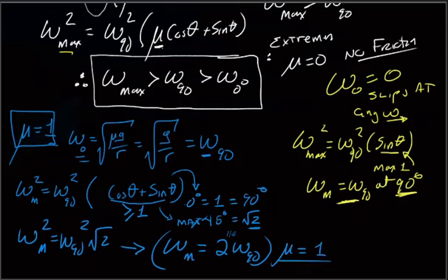So under all cases, we're not able to reach this at a constant omega if we start at 0 or we start at 90. We would have to have some alpha to reach that value. And for fun, you could try to find that alpha as omega final minus omega initial over t. And if we want to make an average approximation, you could plug in some values and see if we can get it to reach that value. But our model had it as a constant.